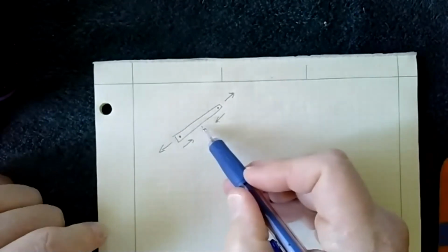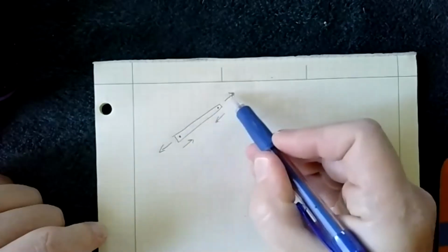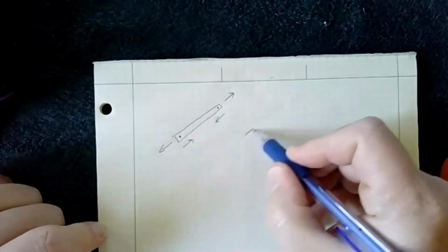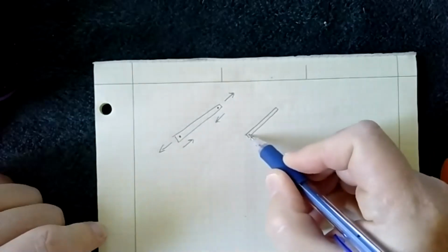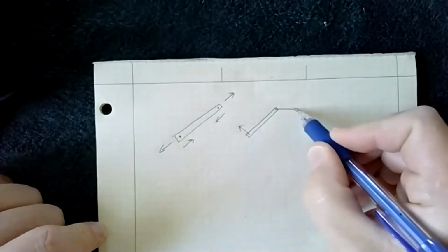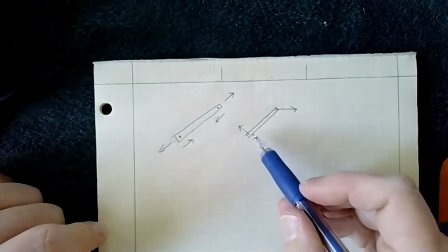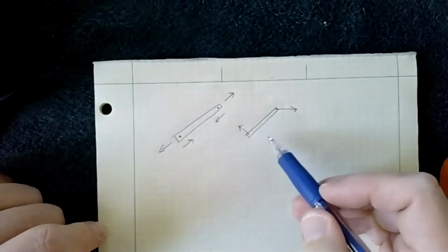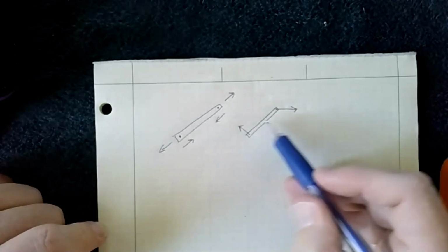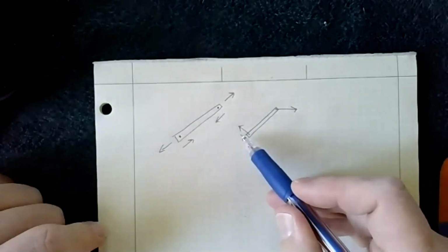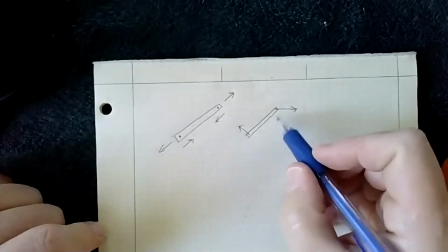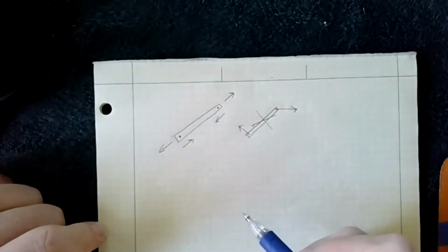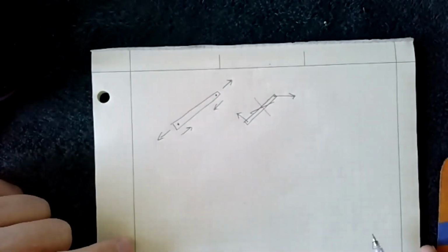So in this context, this member would either be in tension with the arrows going away, or be in compression. If it wasn't the case, if, for example, one force is going that way and one was going that way, then there would be a net rotation or a net moment on this. There would also be a net force in the X and a net force in the Y as these are going in different directions. So this can't exist in statics, at least as a two-force member. I mean, it can exist, but the member won't be in equilibrium.